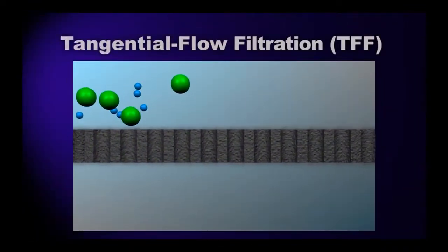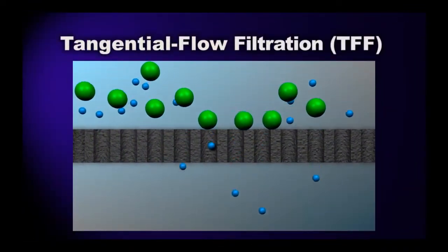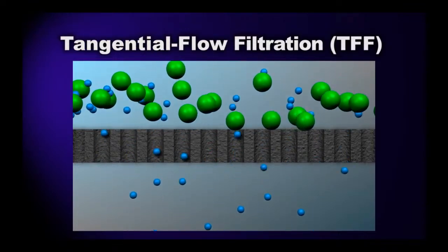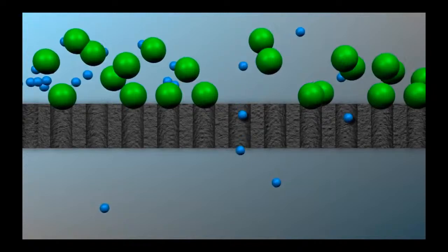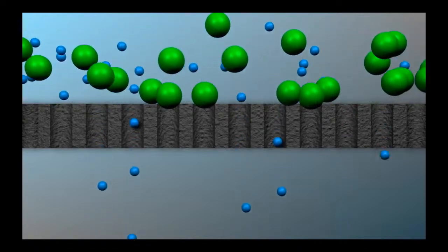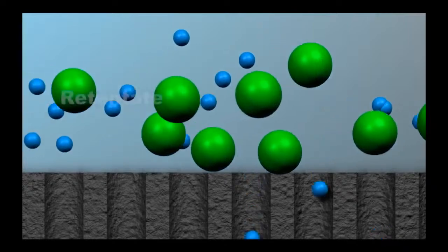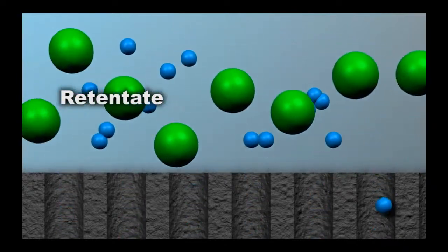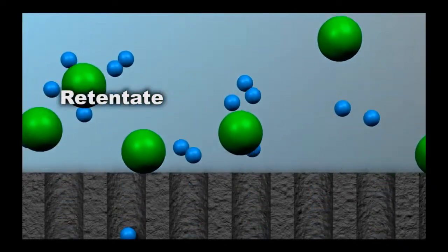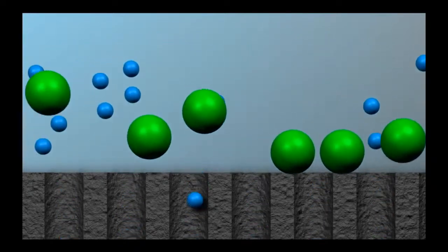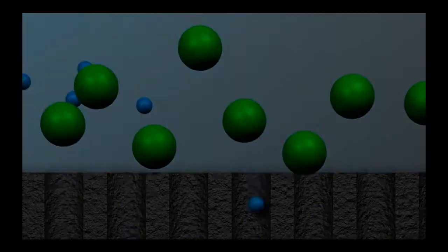In tangential flow filtration, the stream moves across the filter, that is, tangential to the filter, instead of directly at it. The cross-flow current actually picks material back out of the filter media or membrane and into the stream. This retained material, called retentate, is recirculated to the supply tank and will continue to loop through the filter for as long as the process runs.